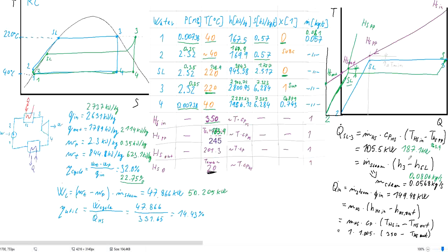So due to the pinch point limits, where we have now lower pressure, so we can get higher amount of heat into the cycle, which we convert with lower efficiency, but still the higher amount of heat overcomes the efficiency and gives us some extra power. You could run optimization to try different pressures and to see where is the optimum pressure to maximize the power output.